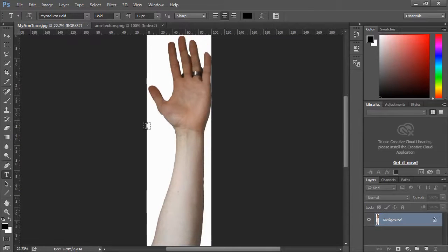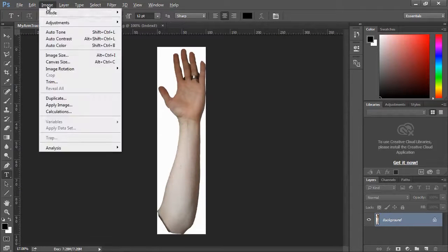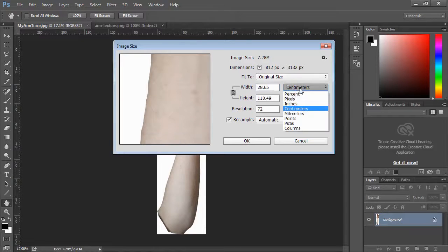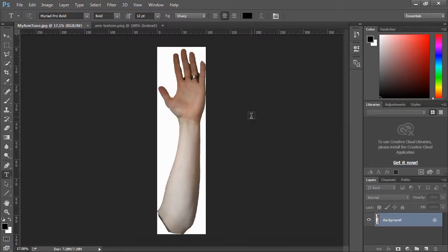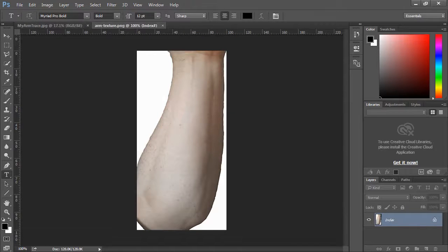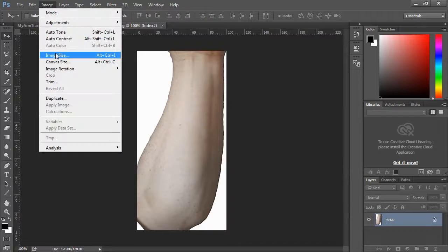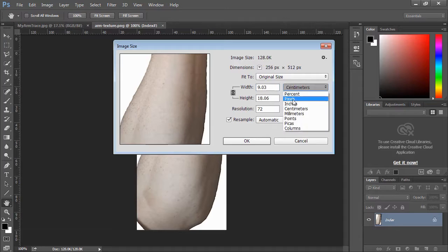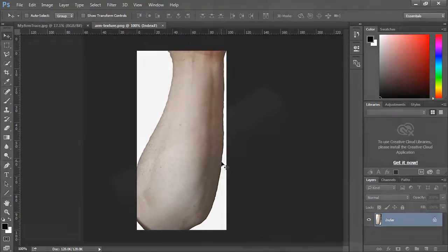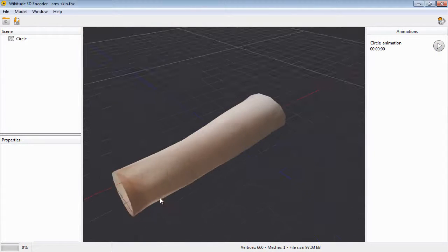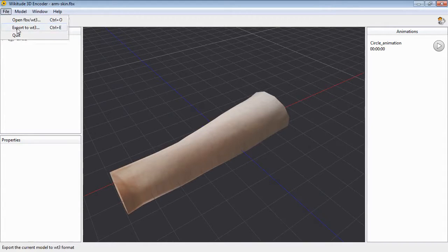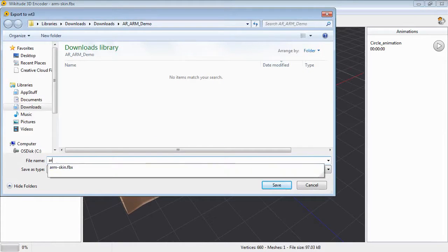So this is the basic, very poor texture that we used. If we go and look at the image size, switch it to pixels, we see it's huge. It's really a bad example. This is a better example. So first of all, I've extended the edge a bit so it didn't have to be too accurate when I'm aligning it. And blended that in. And if we look at the image size, we see those are to a power of 2. 256, 512, 128, 64. Alright, those are all powers of 2. And that's a better image to use as a texture.